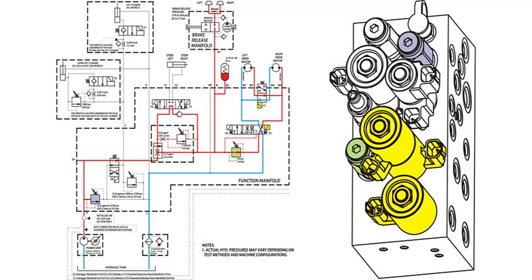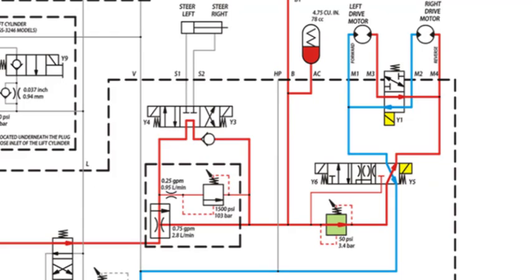In a series circuit, we saw up to 4 gallons per minute entering the right drive motor. That meant that 4 gallons per minute was exhausted from the first drive motor to the second drive motor. When the series parallel valve is shifted, pump flow is exposed to both drive motors. If both tires maintain positive traction and the machine is driven in a straight line, theoretically they will each utilize half of the pump flow.